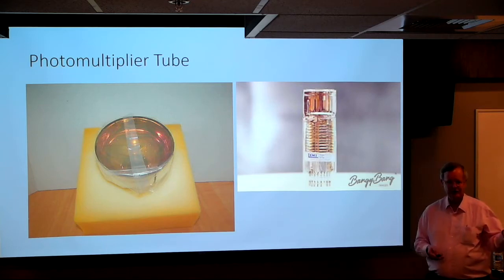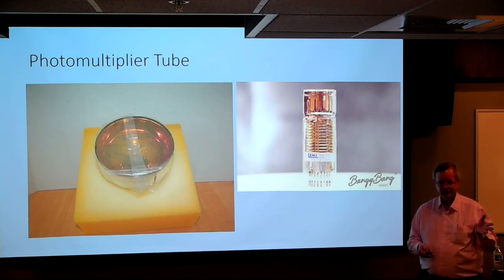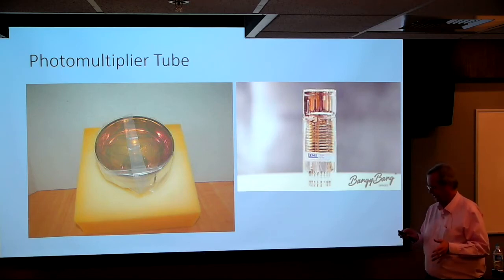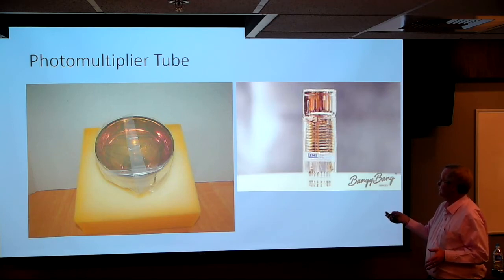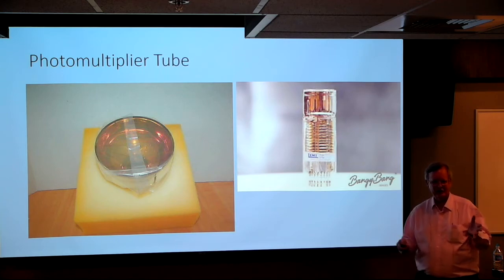These had been made for 10 or more years in different satellite missions. They're having a problem because they were producing particles in there that were conductive. They were actually slightly larger than the spacing between these dynode elements. And of course, if you short out a stage, the gain's down by a factor of 3, and you don't have what you want. So they were presenting me with making a decision.